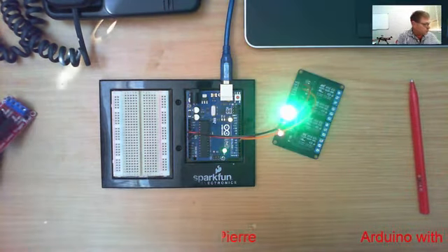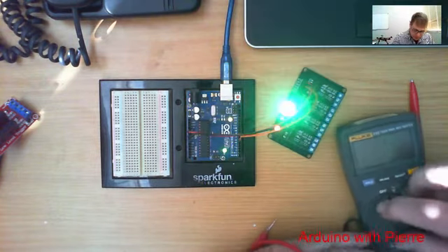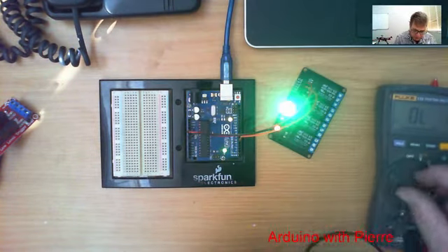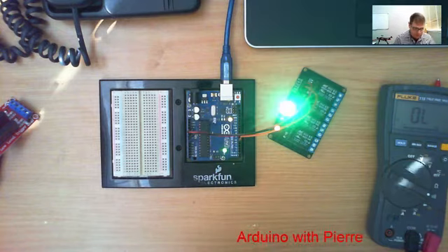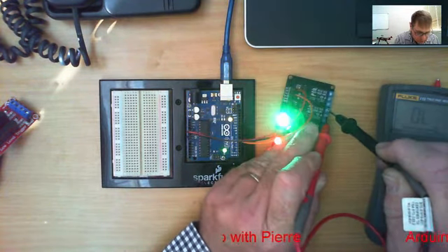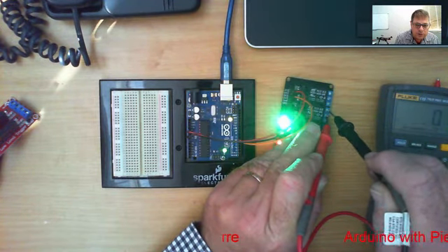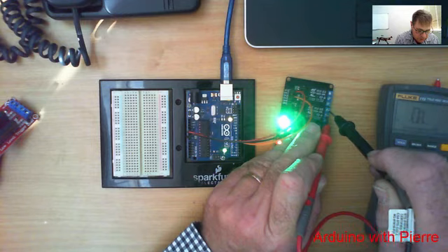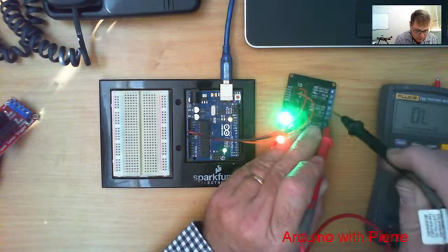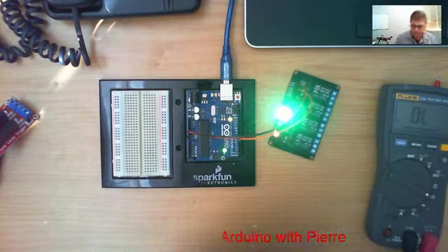And if I take a multimeter and put that to continuity, I can go on there on relay 2, and you can see the multimeter is also showing that that contact is opening and closing between those 2 points.